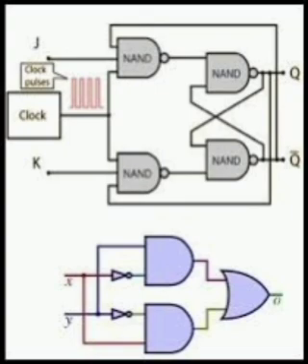possible output lines. Other names of demultiplexer are one-to-many circuit or data distributor circuit. Number of select lines is log n base 2, where n is the number of output lines.